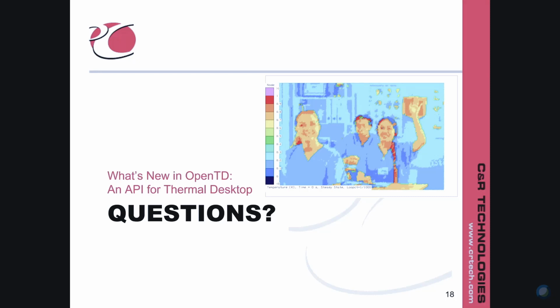Oh yeah, and Hume makes a really good point here. For stuff that I haven't implemented, some of our smart OpenTD users have figured out how to use the OpenTD send command, which allows you to send an AutoCAD command to a Thermal Desktop session. Some of our smart users have found workarounds for things that I haven't implemented yet. So you may be able to do the things you want to do even if they're not explicitly implemented yet in OpenTD by using the send command, which takes a string that goes to the AutoCAD console.